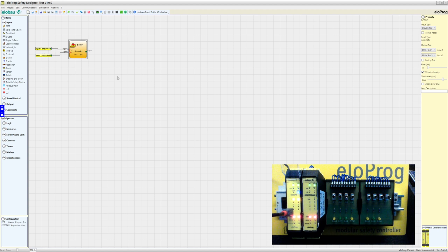This is also very important for diagnostic, and so I can always recommend to choose this option. And if you like, you can have an additional output for error messaging, but please be careful because each output you activate has to be assigned somewhere in your configuration. If this output is not assigned or wired here, you will get also an error message.